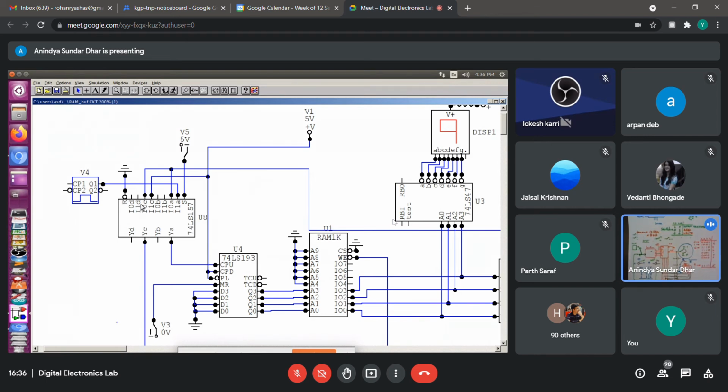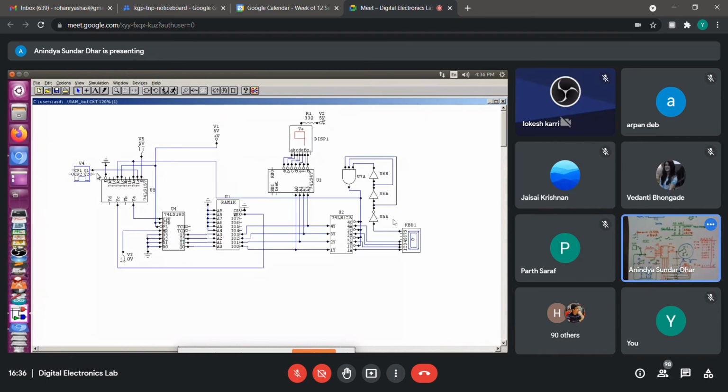Whereas the other one, that is I0C, when I set it in the write mode, at that time this is coming from the same AND gate, right? So this arrangement, I have made it like this. So you can do a separate arrangement also. I mean, you need not really have to follow this. So if I try to simulate that, I am clearing this one. So I need to first write. So for that one, where should I throw this switch, to 1 or 0, what you feel? 0. To 0. Okay, so I am throwing this switch to 0.